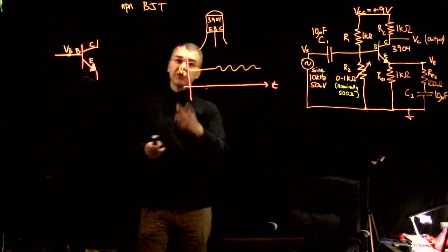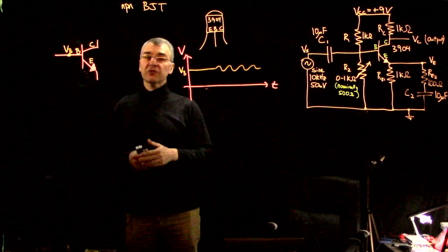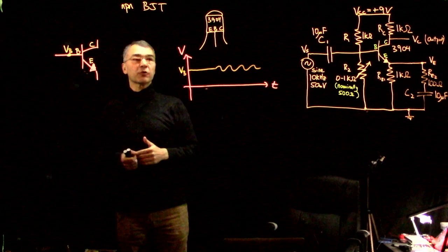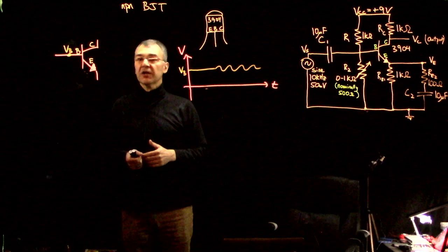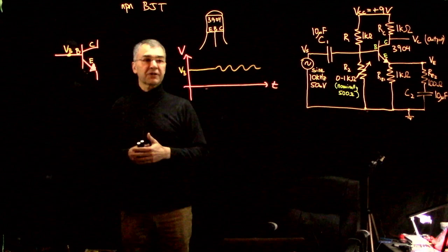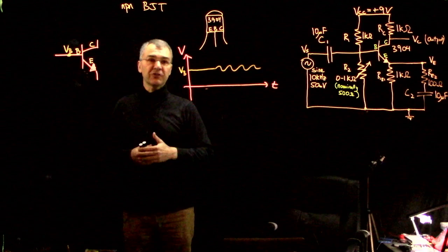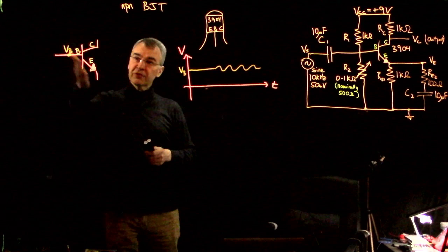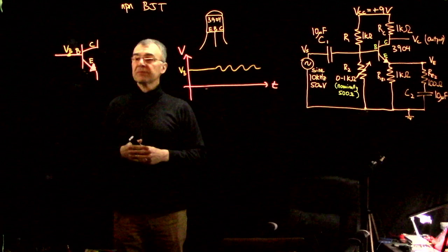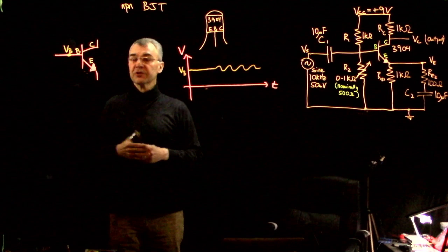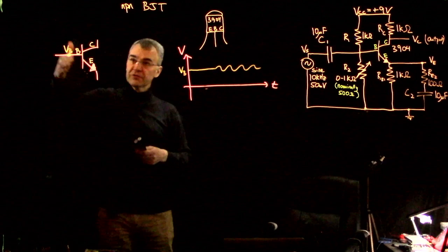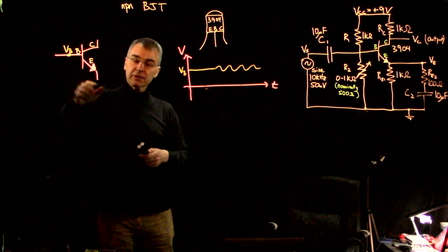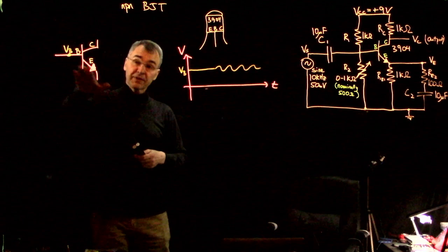And notice I lifted this up above 0 because we want to make the transistor be active. Normally we have this biasing network to do that for us, or there are other tricks we could use. But let's just say we make life simple for ourselves by introducing a DC offset. Somehow we want to make sure that this base-emitter diode-like junction is active. We want the transistor to be active. If we lift this up a little bit above ground, then actually we could just ground the emitter, and that would turn on the transistor.